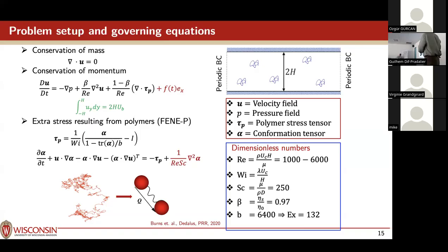Another aspect of the model: this is the evolution equation for the conformation tensor Q. In reality, there's a very tiny diffusion term, because polymer molecules have a finite but very tiny diffusivity. Classically, that diffusivity is neglected, but that causes numerical problems, and so we add a very small but still artificially large stress diffusion.